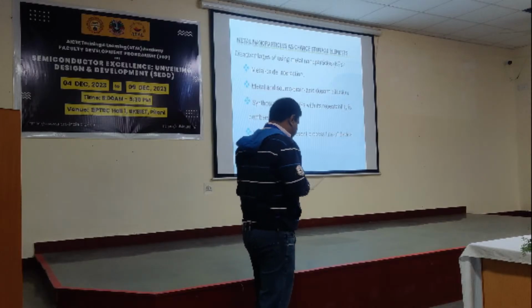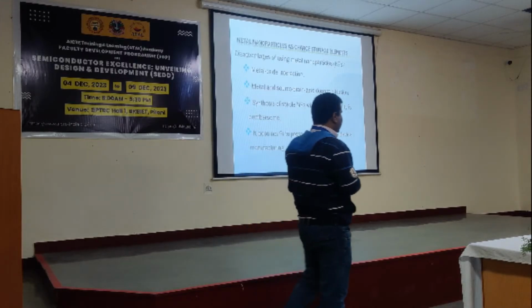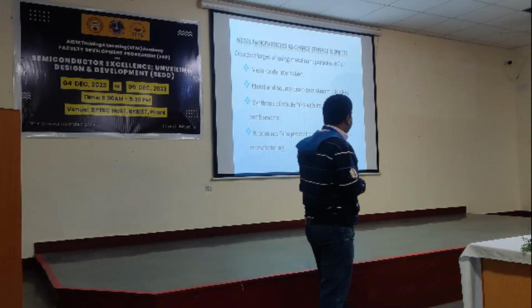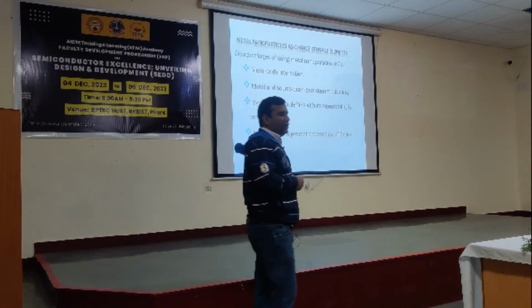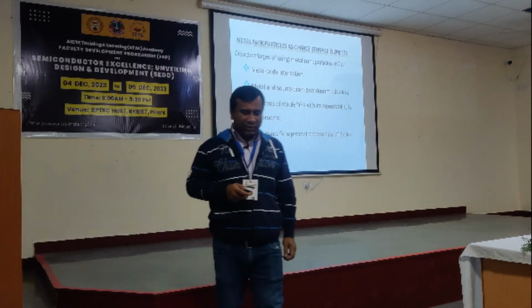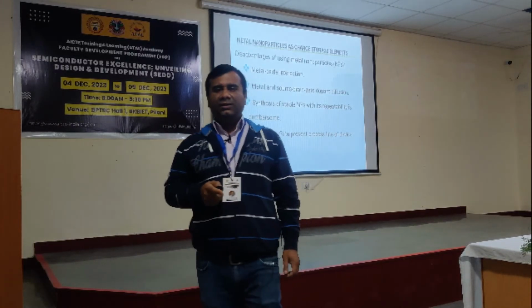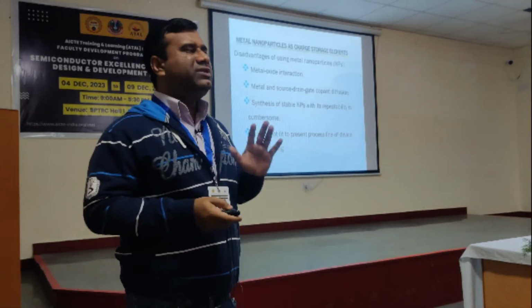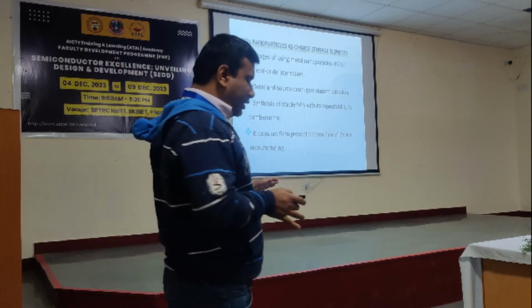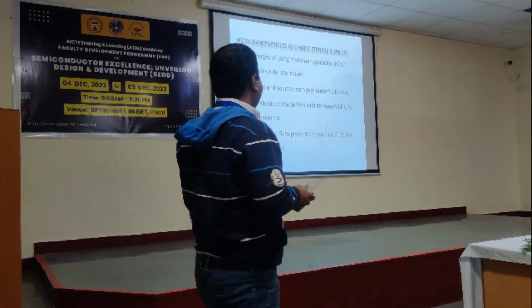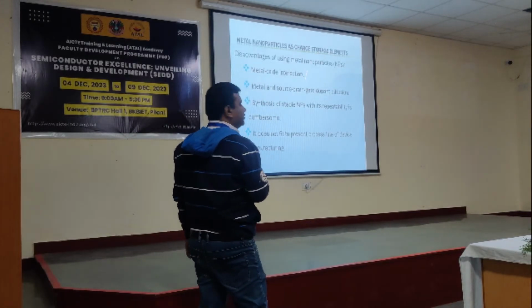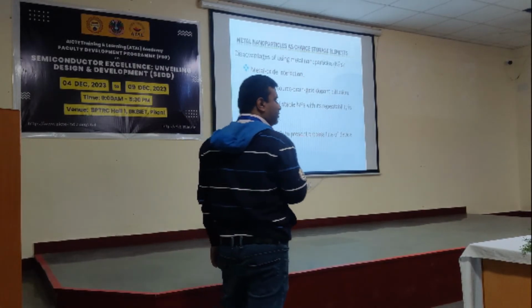Now, through literature survey, you can also see that instead of using quantum dots as a charge storing element, I am telling you again, I have used the quantum dot as a charge storing element because you are talking about MOS devices for non-volatile flash memory application, right? So there should be some material, in terms of nanomaterial, nanocrystal or quantum dot. Previously people used metal nanoparticles, silver nanoparticles, gold nanoparticles, something like that.